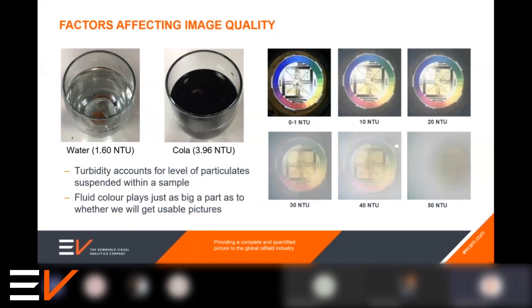So again, a lot of work goes into the preparation, and usually if you do the homework up front, then when you come to do the job, it's relatively straightforward and successful. And with the type of work we've been doing in North America on hydraulic fracturing and assessment of perforations, we've got some very, very good cleanup procedures that actually we've in some cases cleaned up the well way beyond what we needed to do. And then we've learned to relax the cleanup to get to a happy medium where we're not spending too much time and cost, but we're also getting the images of the quality.